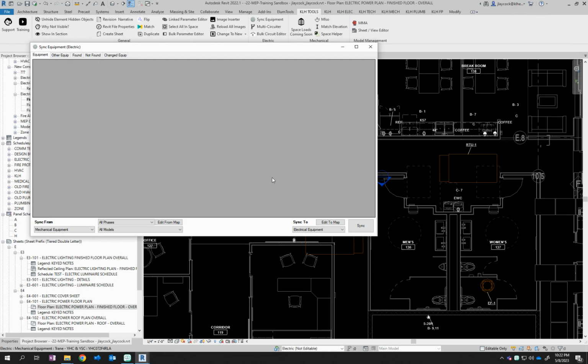electrical connection family. So that could be either a piece of electrical equipment type, or it could be a fixture type. It kind of depends on how you have your family set up. So it's flexible to do either. For this one, I'm going to do electrical equipment, and it'll bring up all my electrical equipment options there when I'm mapping. And you'll see that next.